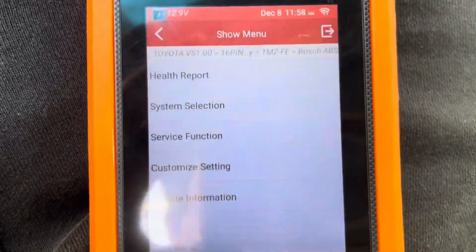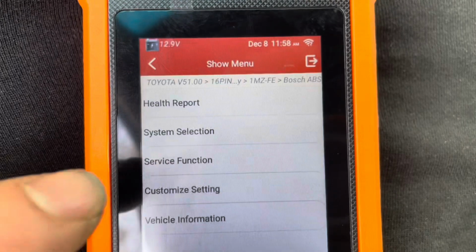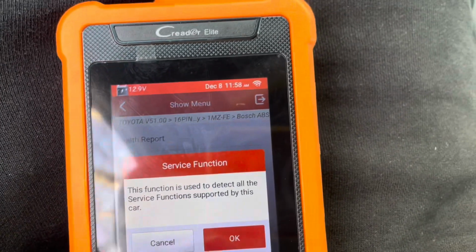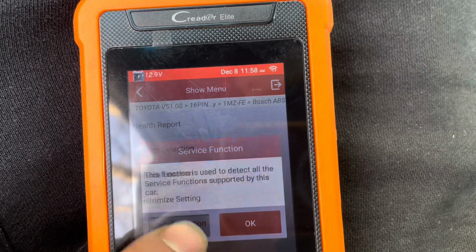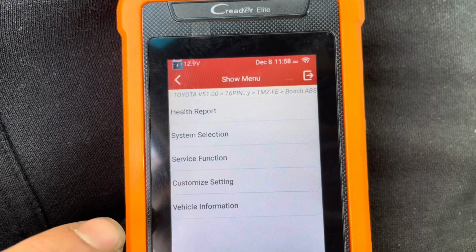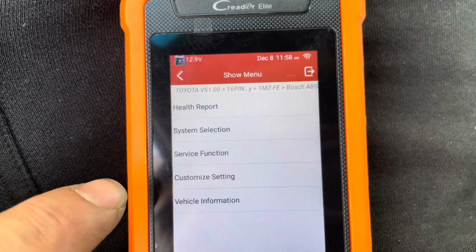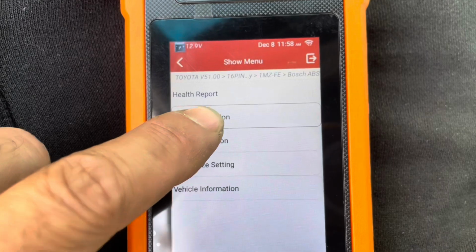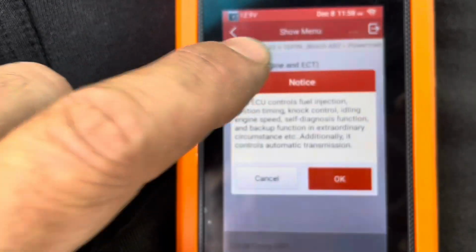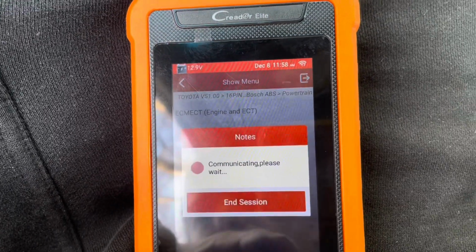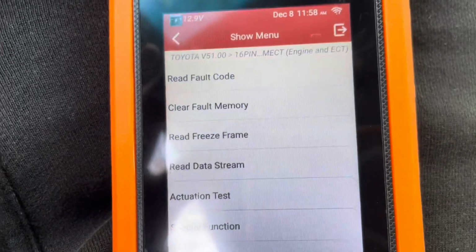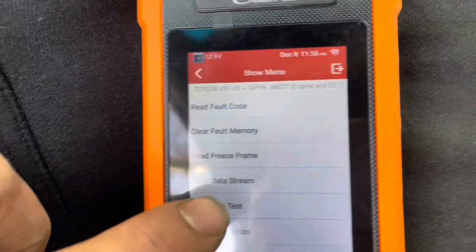What I really want to do is have my scan tool run the evap test and show me the pressure along the way. But apparently I either can't figure out how to make it work, or this Launch Creator tool that's supposed to do everything on a Toyota doesn't show it. It does actuate the switches, so that's helpful troubleshooting, but I want to see the vapor pressure during the evap test, and it just doesn't show it. I went as far as to purchase the Harbor Freight Icon T7 scan tool, only to get it home and find out that it essentially has the exact same software as this Launch tool, and it also doesn't show the vapor pressure during the evap test.